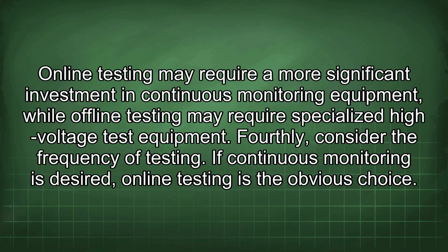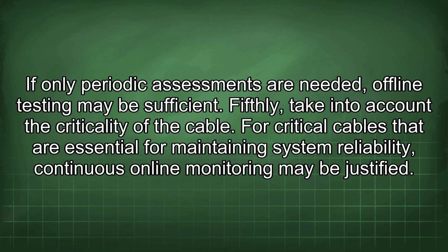Online testing may require a more significant investment in continuous monitoring equipment, while offline testing may require specialized high-voltage test equipment. Fourthly, consider the frequency of testing. If continuous monitoring is desired, online testing is the obvious choice. If only periodic assessments are needed, offline testing may be sufficient. Fifthly, take into account the criticality of the cable.